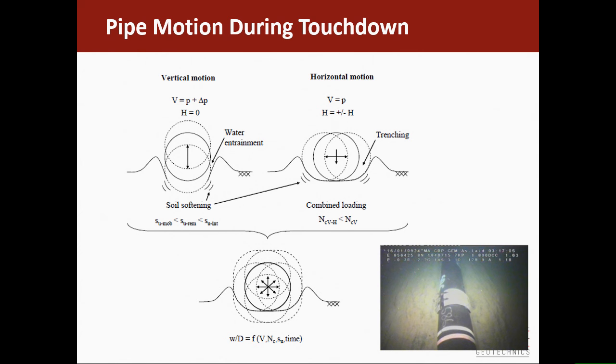And just to illustrate how much they do embed into the seabed, that's a 24-inch pipeline offshore India on soft clay. And you can see how it's gone into basically half its diameter just by weight and lay process. You will often, or nearly always, get a slight berm there if it embeds as well.